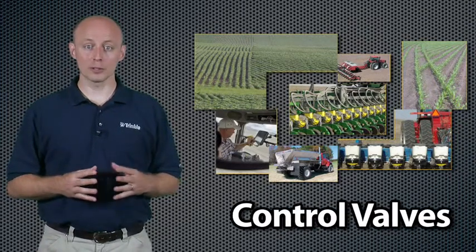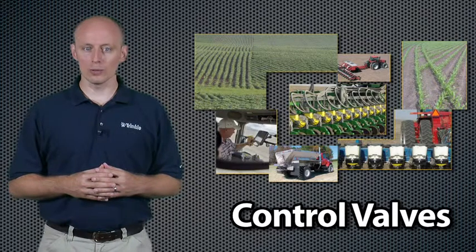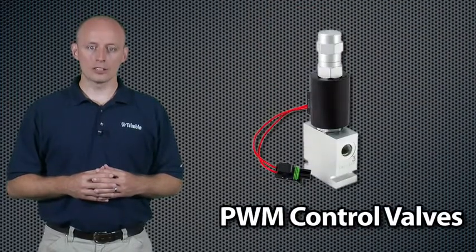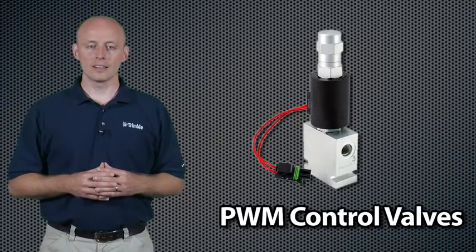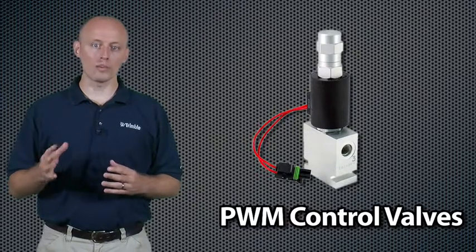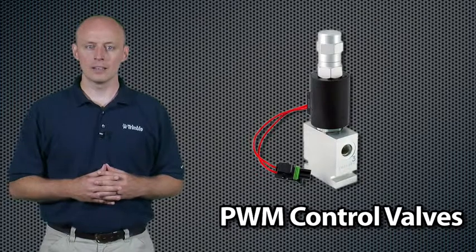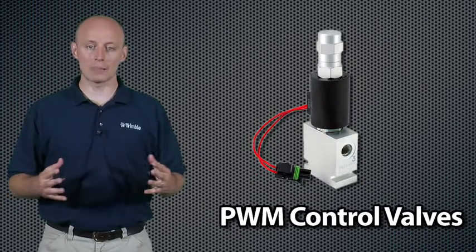The second set of critical components for the True Application system is control valves. These valves make it possible to control and adjust the specific operations that are going on when planting, spraying, or spreading. Hydraulic PWM control valves are used to control various aspects of the True Application system. These valves fully or partially open or close in response to the signals received from the application system. This opening and closing gives critical adjustments to the components in the flow and application system.